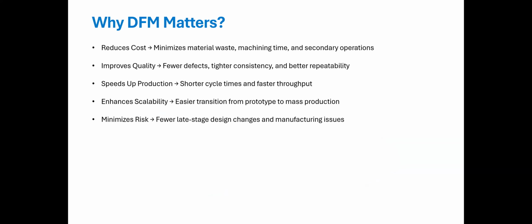All right, moving on. So, why does DFM even matter? DFM is crucial because it ensures that the design of a product is not only aesthetically pleasing, but also practical for manufacturing. At the end of the day, as an engineer, you don't want to give your machinist a headache. I've done it in the past. It's not fun. But by integrating manufacturing considerations in the design process, DFM helps reduce costs by minimizing material waste, machining time, and secondary operations.